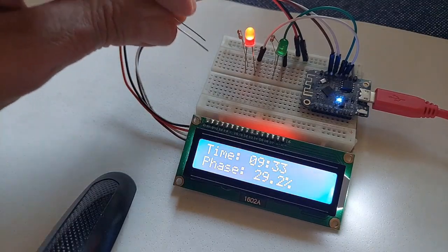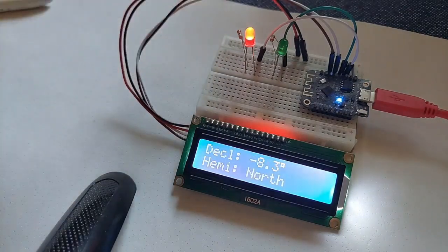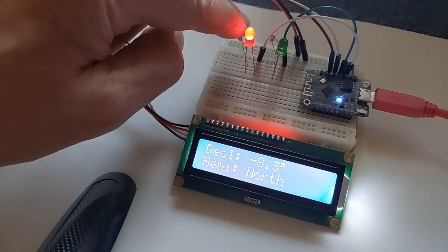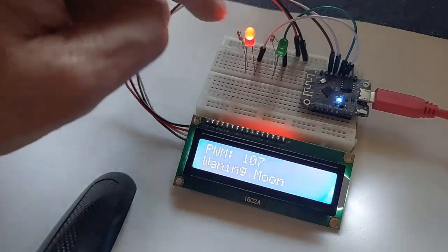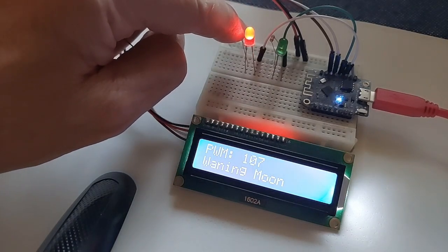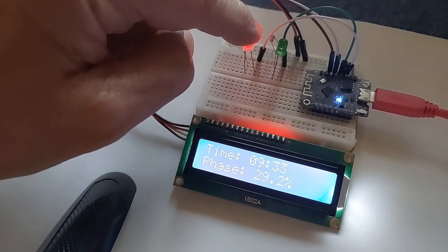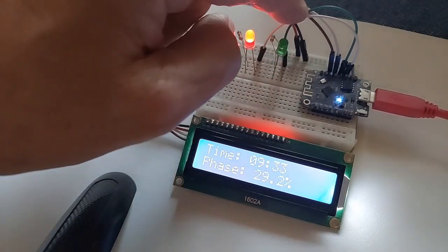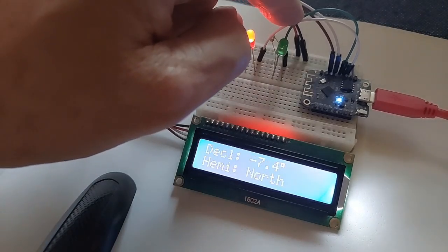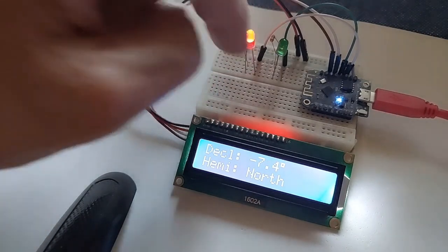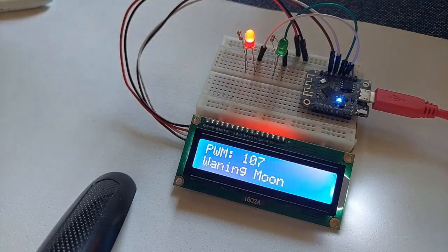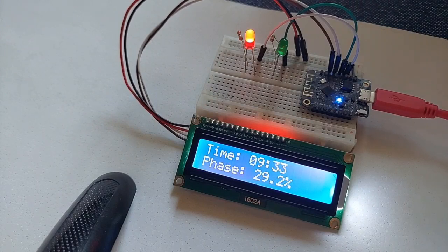So you put the negative on the resistor and you ground the resistor, okay? Otherwise it will burn your LED. You ground the resistor on the shorter pin, and then you put the D, in this case D4, on the longer pin, which is positive. That brings electricity in and electricity out on the ground. Okay, so remember that, but I'm sure when you get to this point you should probably know that. All right, let's go back to the code now.